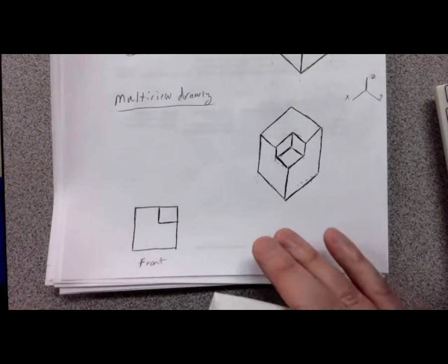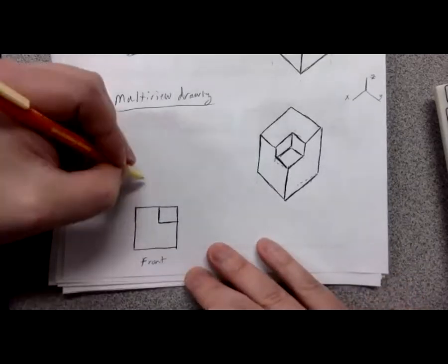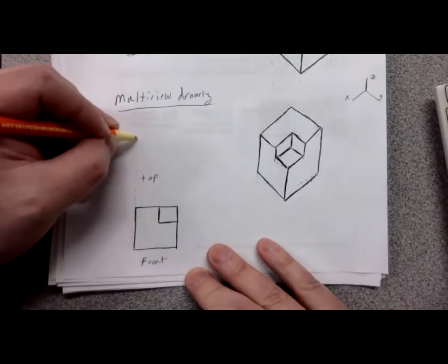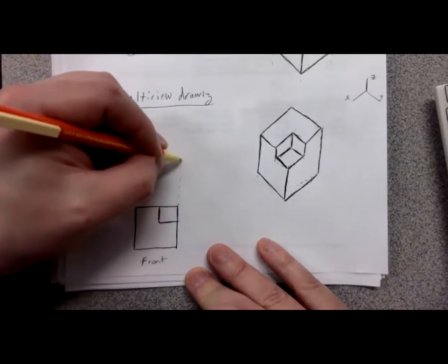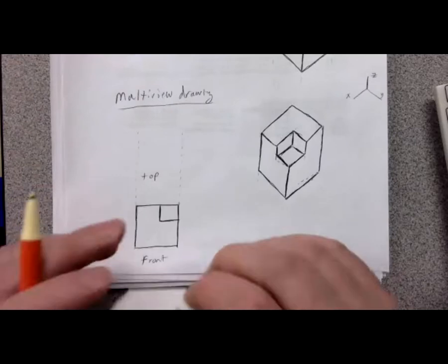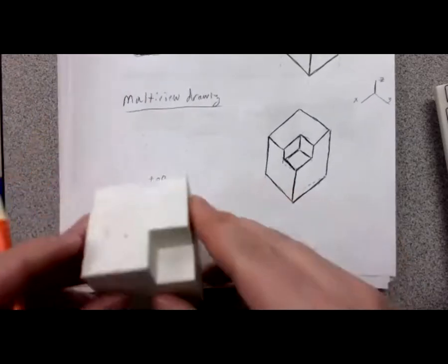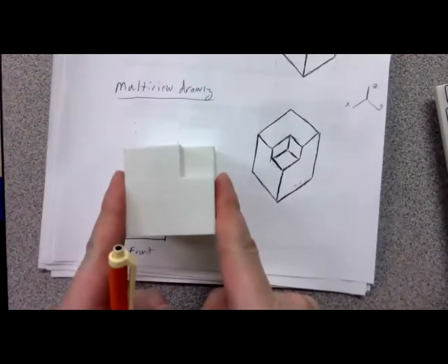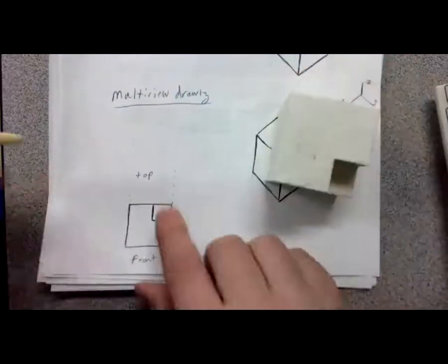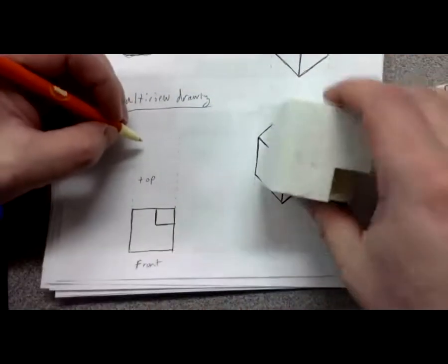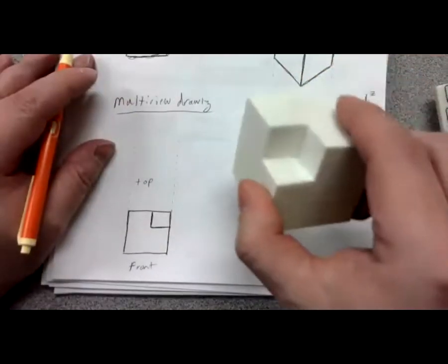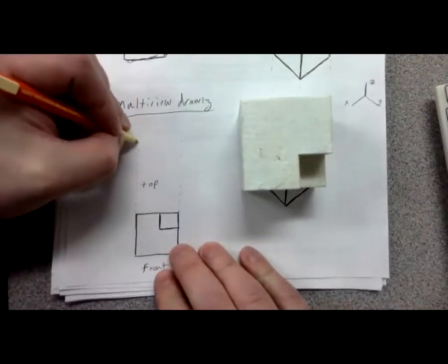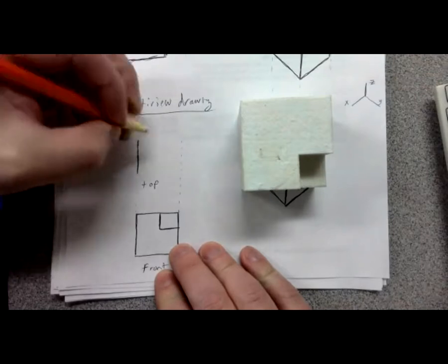Now, as I was saying earlier, really important, these need to line up. For your top projection, you can extend dotted lines up here if you like. Your top projection will have the same width as your front. Because if this is the front, this is the top. This width is this width. They should line up. They should work together. So I've extended dotted lines up here because my top projection, which I just set on my top right there, is the whole thing. That's the top. The top has the same width as the front.